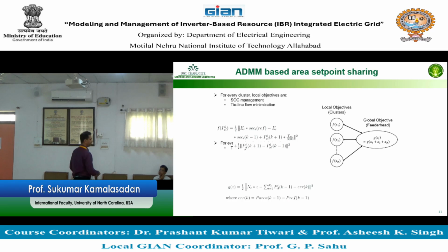When frequency regulation happens, it can go all the way to the distribution network in the form of power. So I can say to the group, I need this power. Not a flat 100 kW or 200 kW, but a changing power with respect to time, and you can ask for that to maintain the frequency. This is called ancillary service supported by devices in the field.